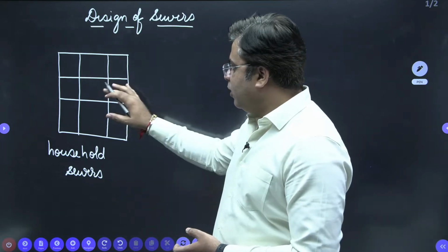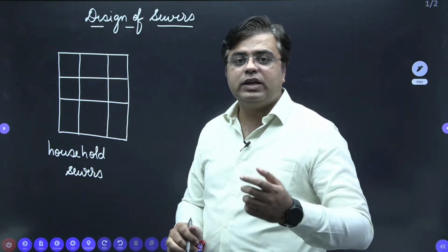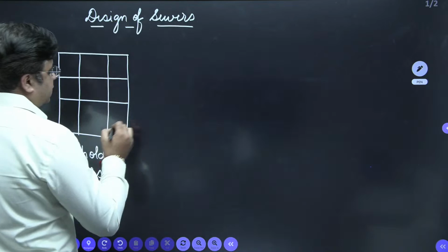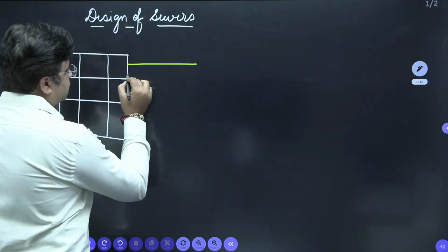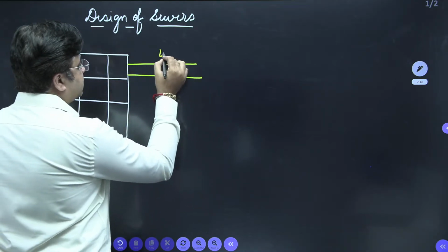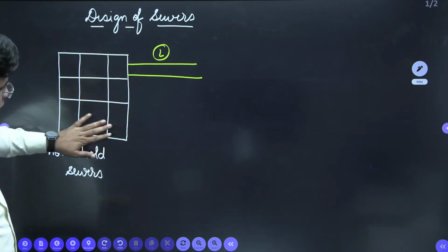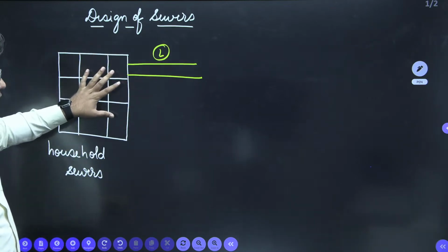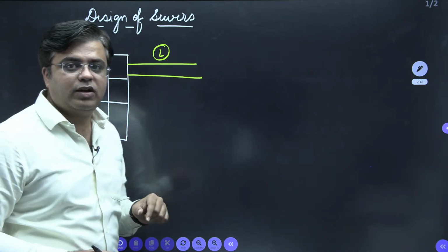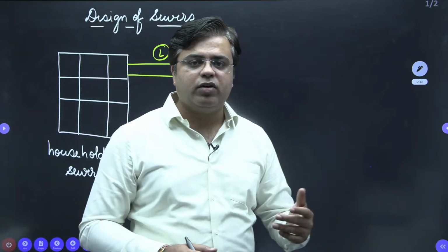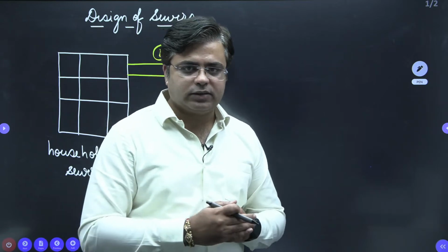Okay. From different houses, this wastewater is collected using laterals. So from the household sewer, the wastewater is collected using laterals like this, right? All the pipes which are laid at your place are known as household sewers. From the household sewer, it is taken to laterals. Now laterals, where you can see, just outside your house, these drains that you see are termed as laterals.